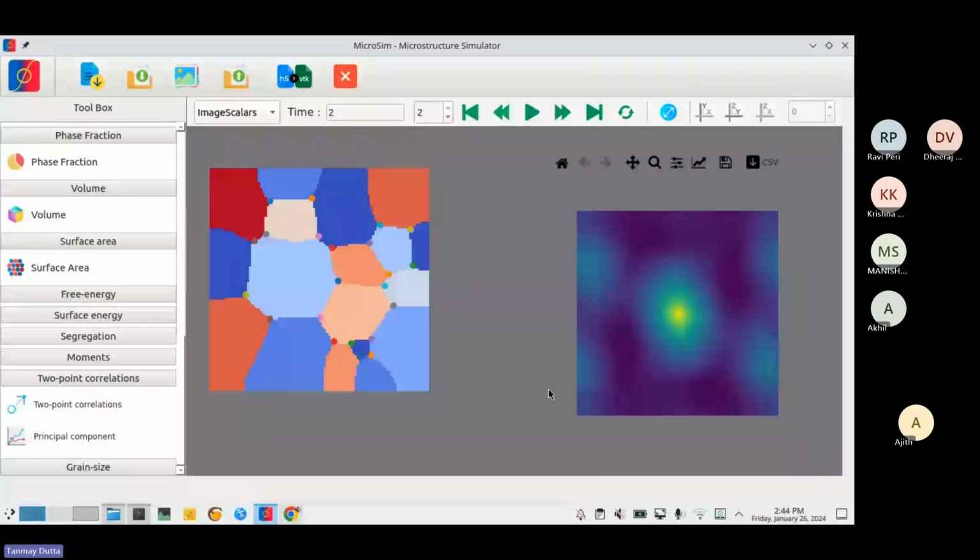If we are talking about vectors, the 0,0 vector has some intensity. It is essentially converting the image into grayscale, and the point at the center is related to the volume fraction. So the color intensity will reflect the volume fraction. Some measures come out immediately, but not all of it is easy to correlate. It gives you essentially another space to represent your microstructure.